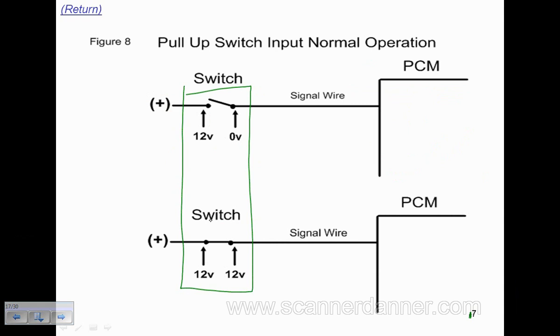Switch open, they were both reading 12 and 0. And I know what you might be thinking is, well, with the switch open on the other design, wasn't this one 12 and this one 0? So they were opposite that way. But on the car, is there a left and right? Well, that wire's going left. Have you ever thought that looking at a connector? No. I can't see which way that wire is going, and that's why I'm challenging you that way.